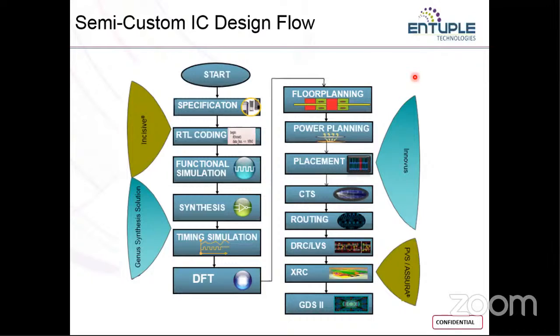Okay, and then you will be translating your block level design or a module level design into standard cells. Okay, and that is what you do as a placement. Only after floor planning and power planning you place your design. And then comes your clock tree synthesis.